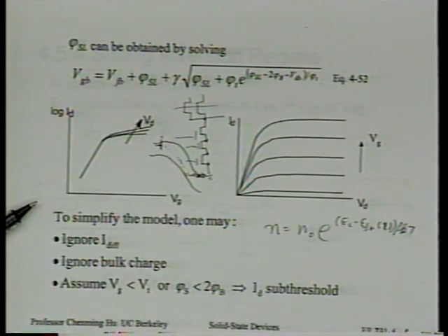Very occasionally, a company may use that in a SPICE model. In the last several years, however, maybe only 2 or 3 years, there seems to be a revival of interest in using this Charge Sheet model for compact modeling, for SPICE modeling. And that's one interesting thing about this Charge Sheet model.